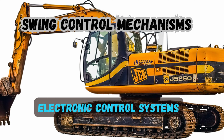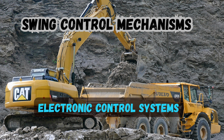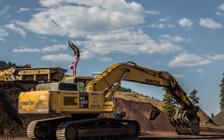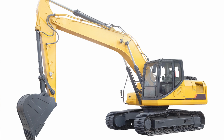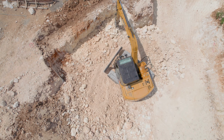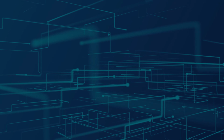In addition, many modern excavators use electronic control systems that precisely regulate hydraulic flow based on operator input and machine conditions. These technologies ensure smooth and controlled swing motion, improving operator comfort while protecting critical components such as the slew bearing, swing gearbox, and structural frame from excessive dynamic stress.